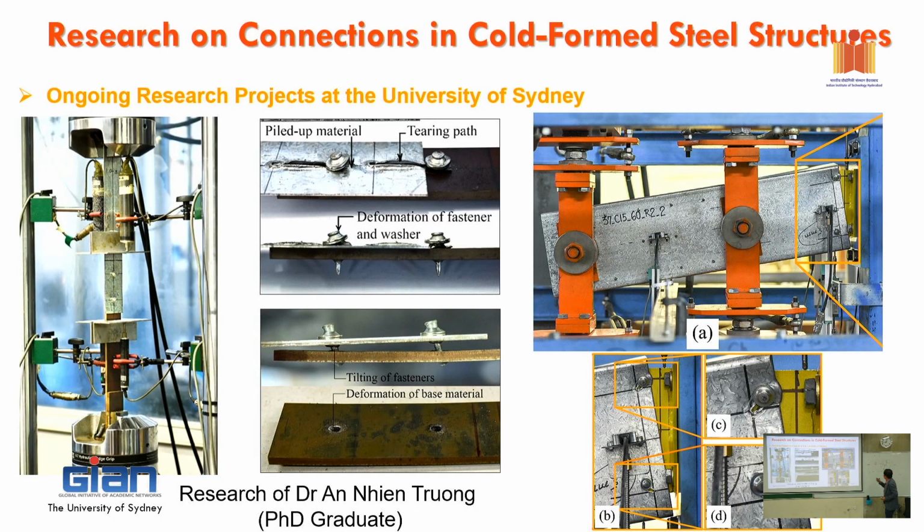The complicated function of this test rig is that the actuators talk together. This one goes down and reads the shear load and then feeds back to the other one, and that one will run up and down. They make sure that we target one ultimate load or whatever we want to target.